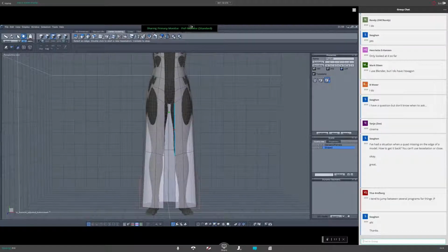And yeah, you guess, if you do this a couple of times, what happened now? Hexagon just lost its little mind. Yay! This is one of the examples I hate about Hexagon. You see now, sometimes you have to trick this. So you end this operation, choose tessellate by slice again, do this again. Now it works. Now we have more or less quartered this skirt, but it can take one more.